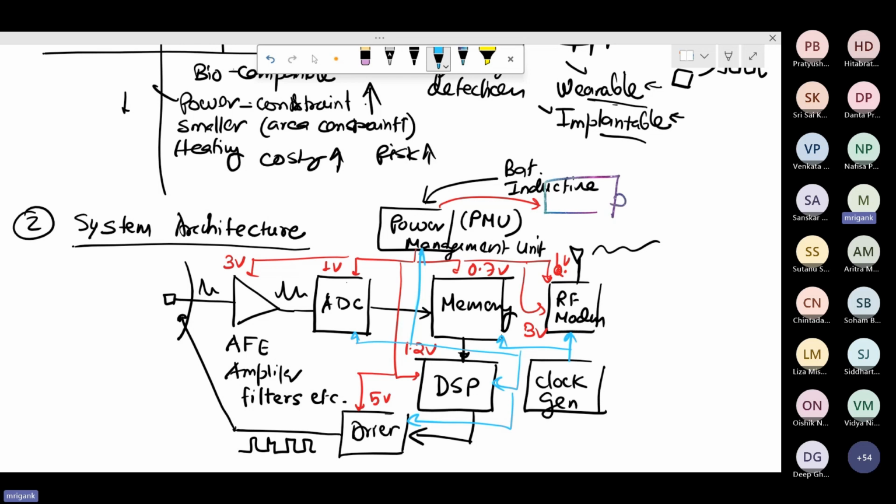When you are doing digital processing, when you have covered the digital circuits course, you know that digital circuits, some of them are combinational, some of them are sequential: flip-flops, registers, counters. All of these require a clock to work. All the sequential circuits require a clock to work. Any digital system, digital architecture, digital module is a combination of sequential and combinational circuits. Therefore, a clock is always required. Even memory is going to run with a clock.